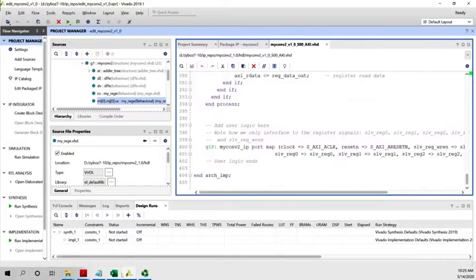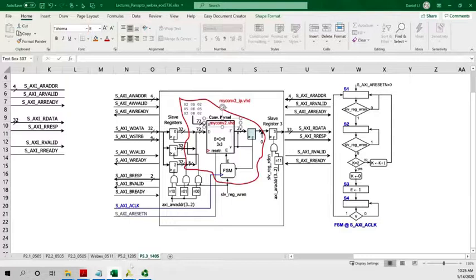So notice one important thing to tell you is that whatever you design, make sure that it receives inputs, and there is a qualifier for the input, and then once the data output is processed and computed and ready to be out, you qualify the output with a V signal. Okay, if you forget to do that, there is no way for the AXI4-Lite interface to know that you have correct data. So you have to do it. Okay, has to be that way, or at least resemble it in some ways.